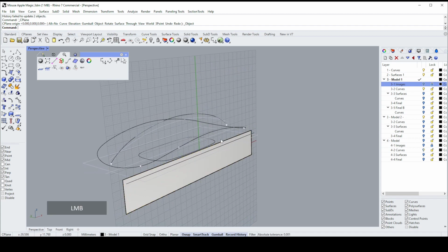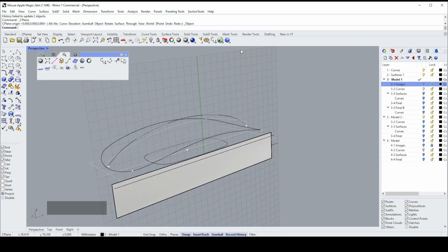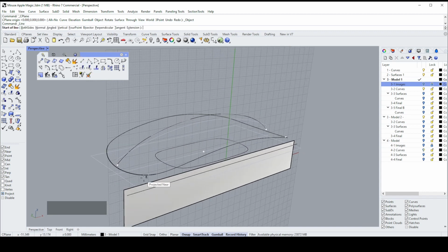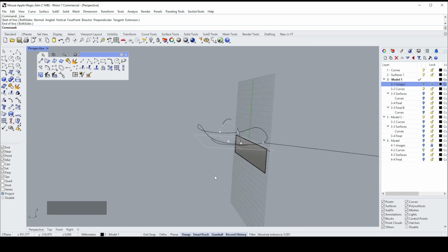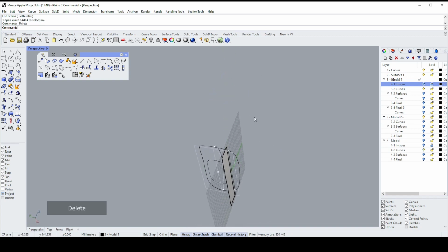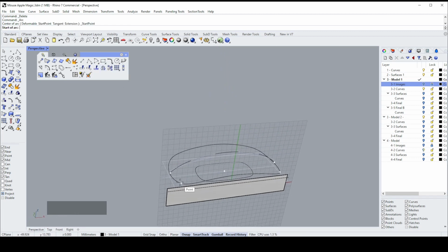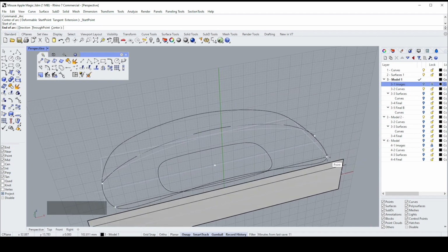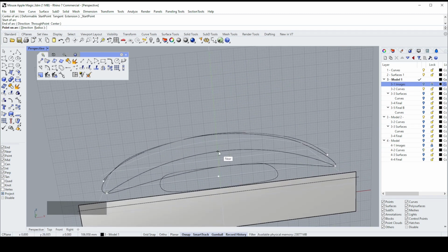Very, very convenient. The other thing I want to do is project. If I click on the project button, that locks everything to the construction plane. So that if I draw a line, if I click on a point, I can try and go out. It looks like I went out, but I didn't. I actually stayed within the bounds of that plane. Okay, so let's select this arc start and end point. And because I've got those points selected, I can now select the points and not worry about not getting the curve to line up. And then drag it to about there.